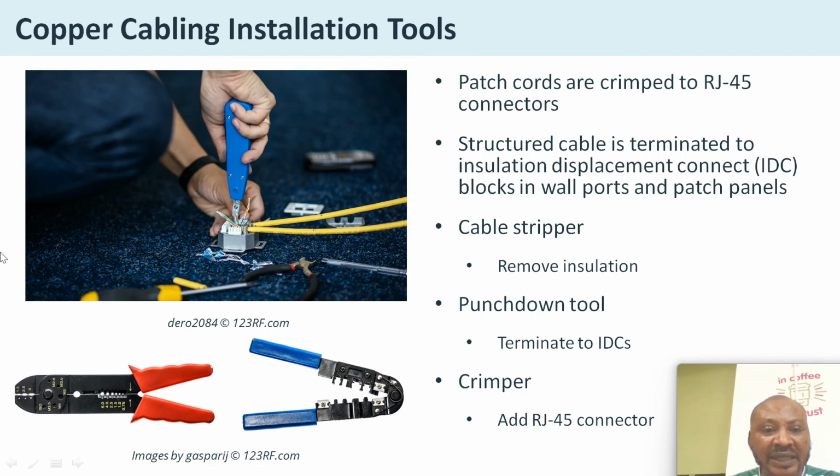Continuation. Now this is a punch down tool. This is a cable, and this connector is what goes to the wall. When you connect a network cable for a computer, it connects to the wall through this connector. Inside, that's how it looks. You just follow the color configuration, the color mode. Where there is blue, they put blue. Where there is green, they put green. Where there is white-blue, you just follow it; you see it on the connector. Then you have the punch, put it in and press it.